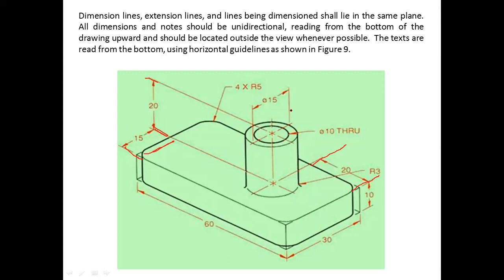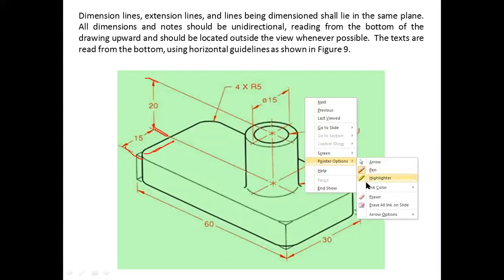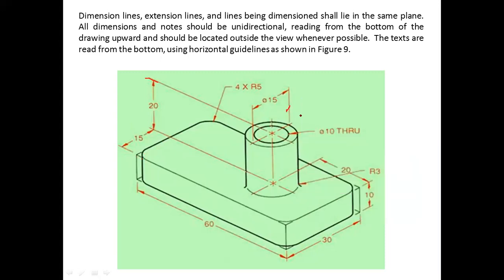So these are called extension lines. I will clear my screen and I will show you extension lines. These are called extension lines. Because we are using those lines for a dimensioning purpose, extending. Otherwise we could have shown it here, but it is avoided. That's why this thickness or height is drawn by extending these lines. These two lines are extended, which is ultimately showing this height, nothing else. But we generally avoid dimensioning within the block itself, or within the isometric view itself.